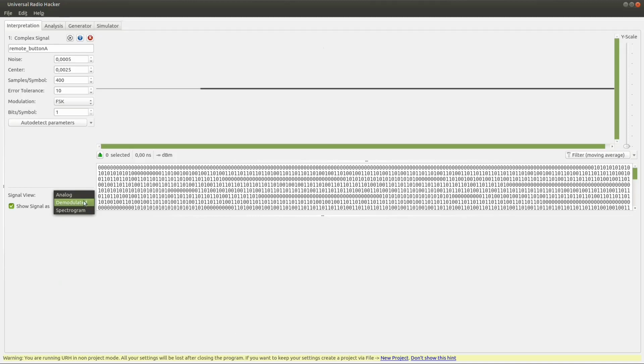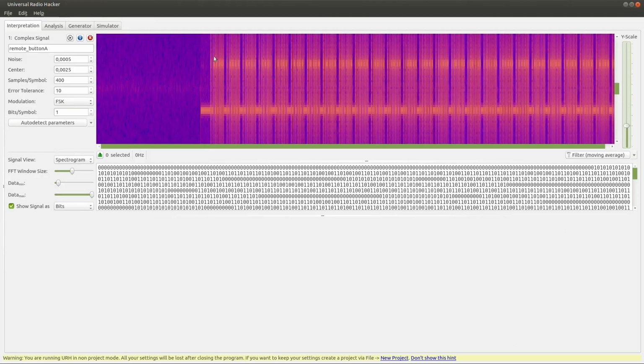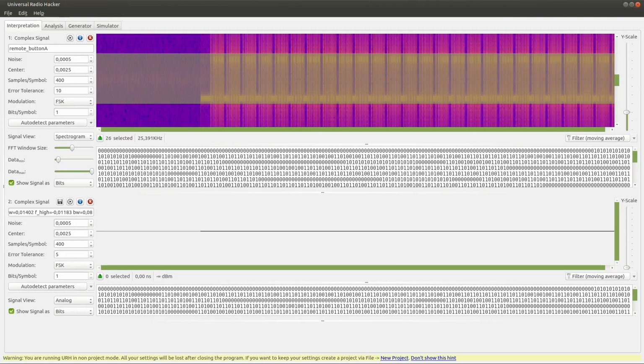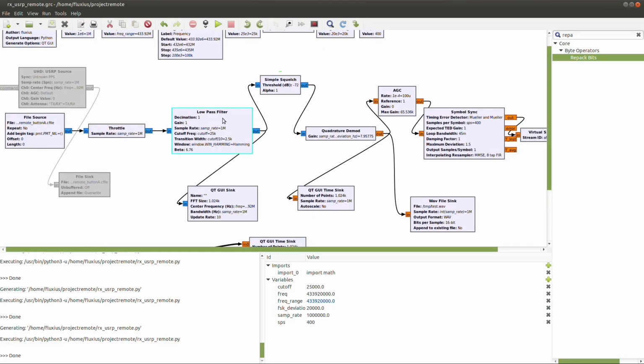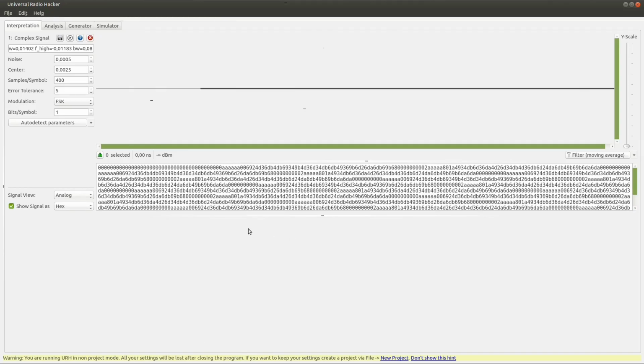But we can also filter it a little, because the bandwidth that we have captured is a bit too much. So we can apply a bandpass filter in here, exactly as we have done in the past. Also, you can get rid of the first signal and focus on this one, which represents, as you guessed, the first AA that we recovered earlier.